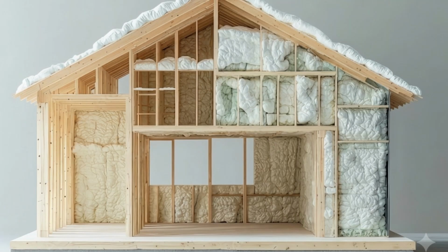We all know if we put a warm coat on, or a coat that's really thick and woolly, it gives us a nice cozy feeling, because it stops the warmness within us from going to the outside air, which would make us feel cold. And it's the same principle when we wrap a house with insulation. That's why we put insulation in the floor and in the walls and in the roofs. It is proven these days that we lose a lot of energy through the floors. That's why we put insulation in the floors. But let's talk about the walls.